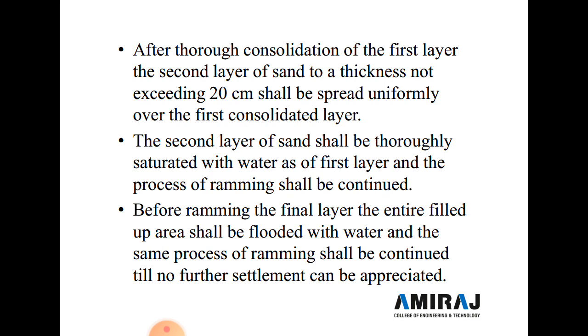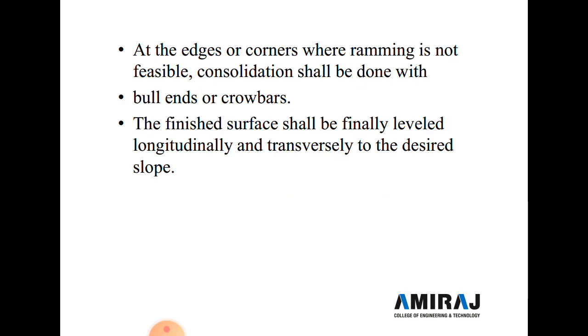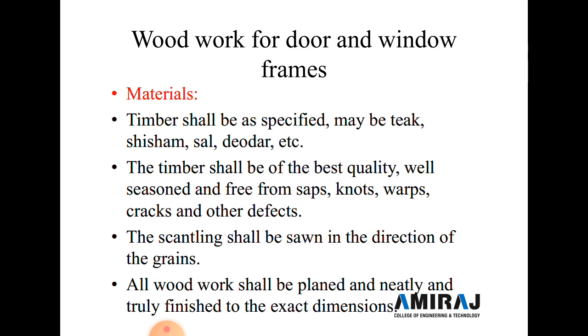So before ramming the final layer, the entire fill up area shall be flooded with water, and the same process of the ramming shall be continued till no further settlement can be appreciated. And at the edge of the corner where ramming is not feasible, consolidation shall be done with bull ends or crowbars, and the finished surface shall be finally leveled longitudinally and transversely to the desired slope.